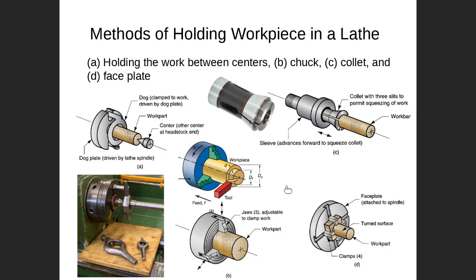However, there are some other ways to hold a workpiece. Like this one, we call it a faceplate. This is a faceplate. It is for holding a non-cylindrical shape. You told me that in a turning operation we create cylindrical shapes, exactly, but the part that we hold is non-cylindrical. Can you see that we cut a cylindrical shape, but the part that we hold is not cylindrical? How to hold it? Then we use what we call a faceplate. We cannot hold it by using a chuck mechanism.